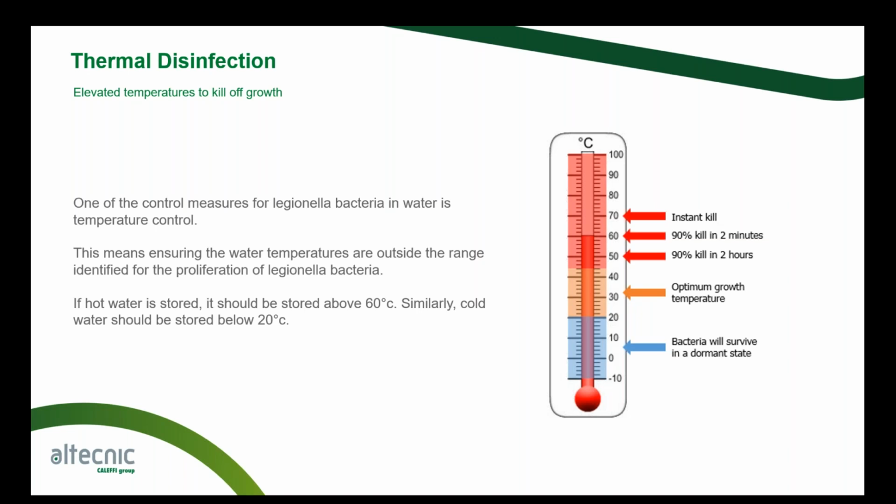Like I say, the bacteria doesn't like it when there's fast flowing, high volume of water. It likes to find dead legs, it likes stagnant water. So we want to keep it moving. But if we look at a bit of a time or temperature scale here, anything sub 20 degrees, the bacteria will survive in a dormant state. And then we start to move up.